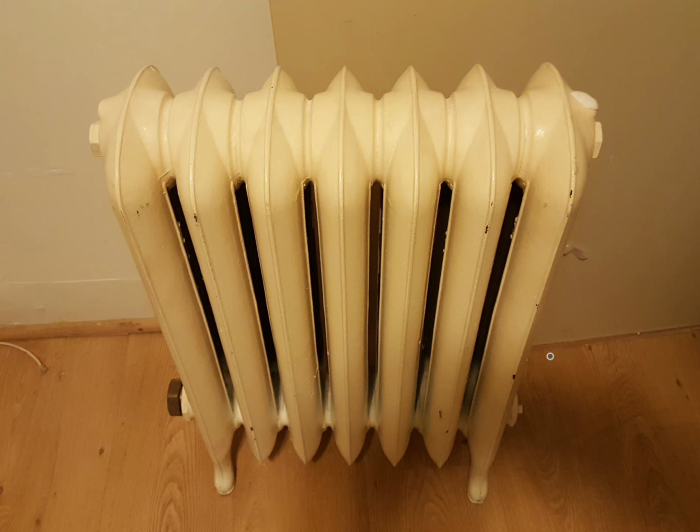Based off of the way the cast iron radiator is constructed, and the fact that it holds its heat for a very long period of time, once that vent locks out, or once it has vented all of the air out of the system, it's pretty much just going to stay locked out and you're not going to hear it again. The only way you typically hear it again is if there are still some air pockets along the bottom portion of the radiator. Then you'll hear it opening up occasionally just to vent out that air. And once that successfully heats up, that vent locks out and you don't hear it again until the heat shuts off and then cycles back on again.